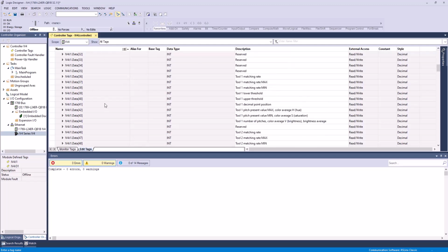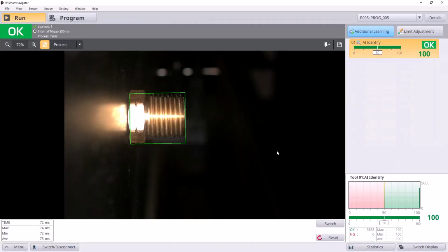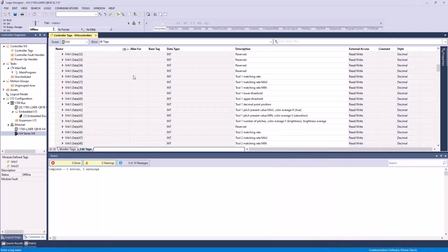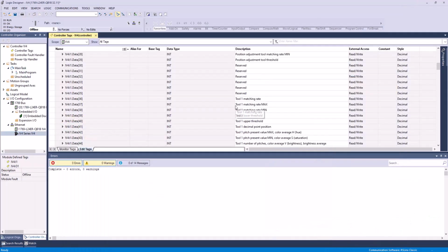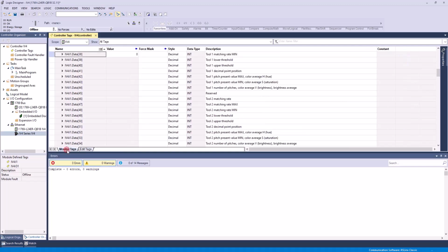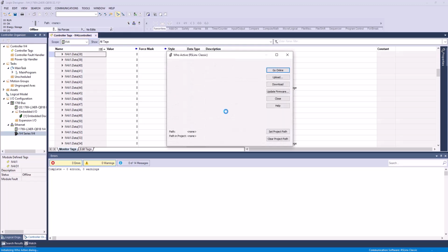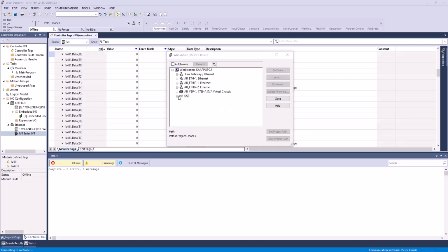All right, from here, because we've already set this for Ethernet IP, and this is already loaded, we're just going to try to go online here, connect the PLC and the device, and we should see all these tags start changing when we go to monitor tags. And we should see these zeros start changing to ones, different integers, etc. So I'll specify my path. In this case, I'm connected via USB. It's the device I'm using, and we'll just hit download.